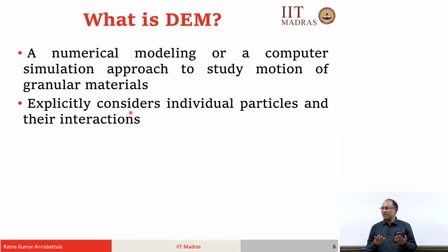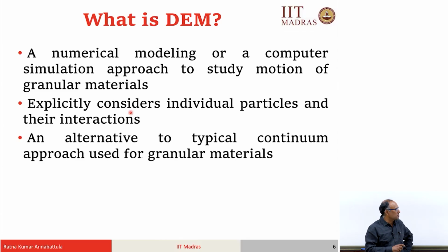At some point of time there may be interaction between two particles, at some other point of time the interaction may not exist. That means the establishment and detachment of contacts happens all the while during the simulation. This is handled by discrete element method very efficiently. So, it is an alternative to the typical continuum approach that we are all familiar with for granular materials, wherein you do not really have access to what is happening at each and every particle level.